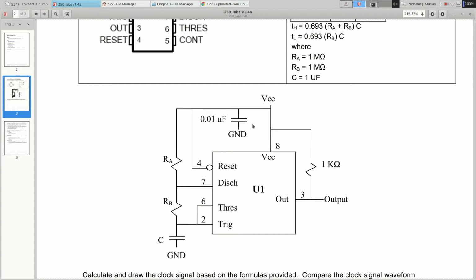We can do whatever we want for output, right? The first thing you're going to want to do, yeah, basically, you could put it into an oscilloscope, you can hook it to an LED. Okay, I would say hook it to an LED and make sure that it's blinking on and off at some easy to notice rate. If it doesn't look like it's blinking, if it's on solidly, check your resistors. Because a lot of times you accidentally put in 1K resistors, and if you do that, it's going to blink on and off really fast, like 1,000 times a second. It's going to look like it's on.